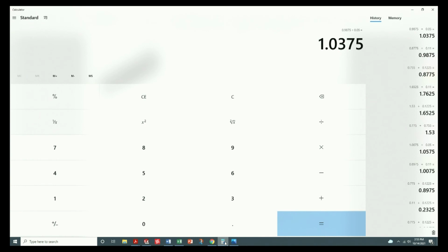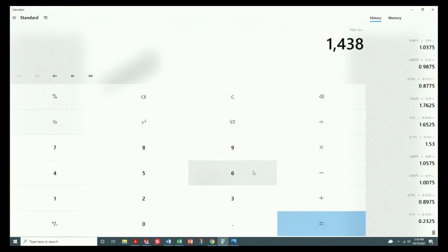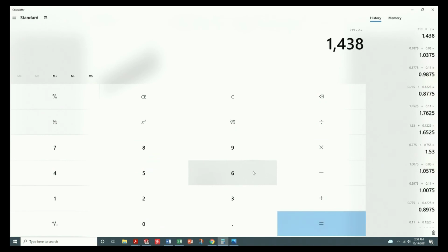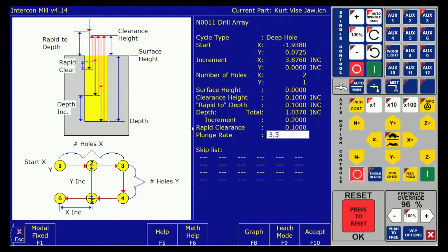Yeah, right. Please give Damon a calculator. So, what did we come up with for an RPM? 719 for an RPM? So it is RPM 719 times the number of flutes times 2, divided by chip load. Our chip load is going to be 2.5 thou. And it's straight multiplication times 0.0025. Our feed rate is 3.5 inches a minute.